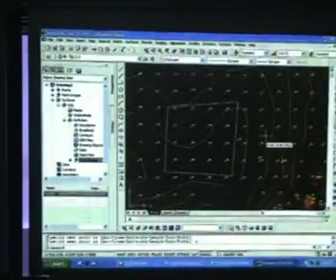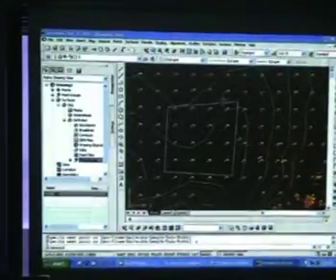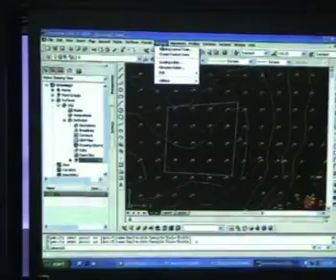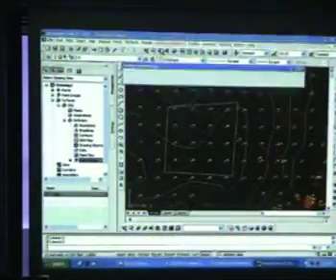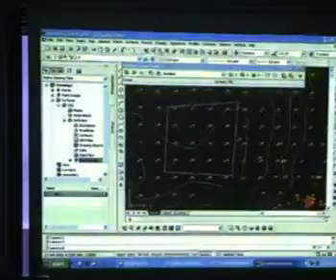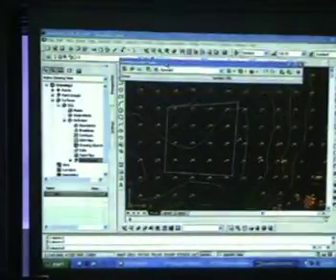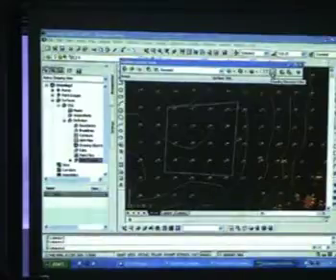But first we need to specify what's the elevation, right? Now we do that during grading. Just go to the grading menu. Go to grading layout tools. Then you have another floating menu on top of it. First we're going to modify the elevation, so we go to the grading elevation editor.